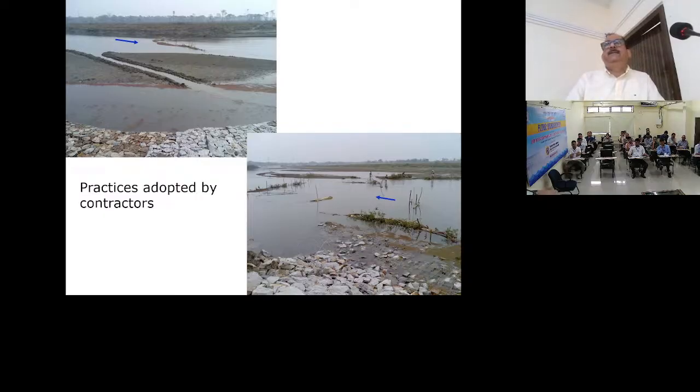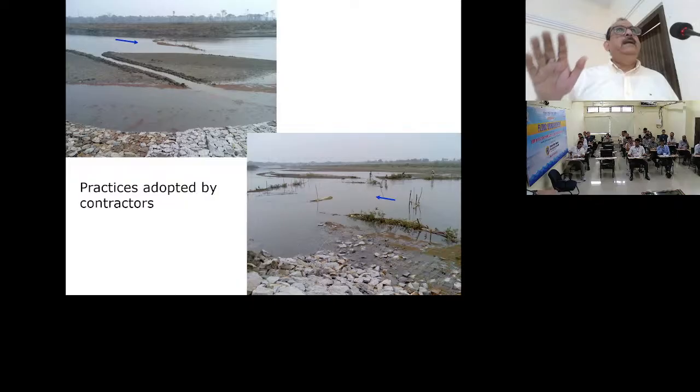let me answer it in a different way. Number one, jute we are trying to use, but the life is very short. The life of synthetic geosynthetics is longer. Jute has a life of 1 year, 2 years. After that it will decay. But it is expected that within that period, the slope will be stabilized. Initially, the jute will protect it, but it will completely decay after 2 years. Then it is believed that the bank is stabilized and it will be protected.